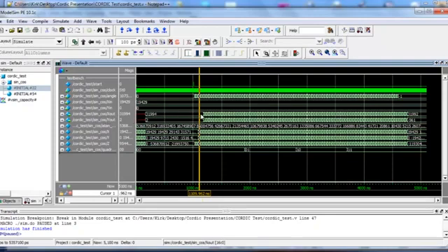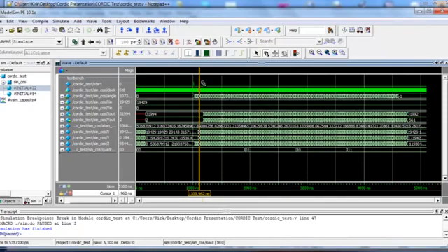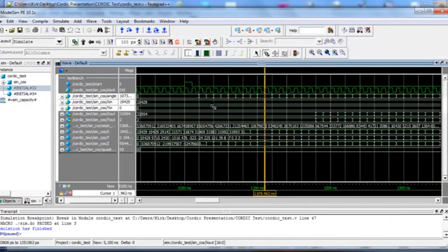And here you can see that every clock cycle the values change. And we'll zoom in here. Then I'm going to show you something more interesting. So let's just zoom in right here at the beginning. So here you see our start signal. Now remember that due to the pipelining of this architecture and how long it takes to get the first result out, you notice from start all the way to where the output actually starts changing is going to be our delay of 16 clocks basically. And that's what we see happening here.